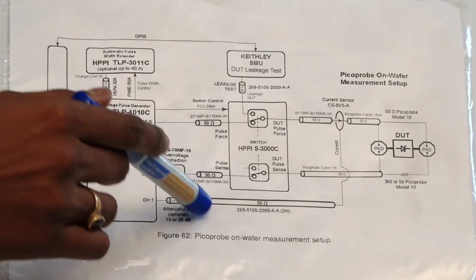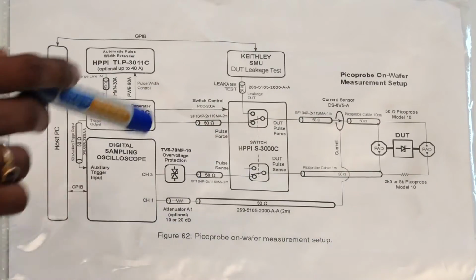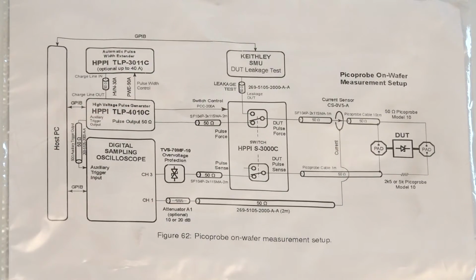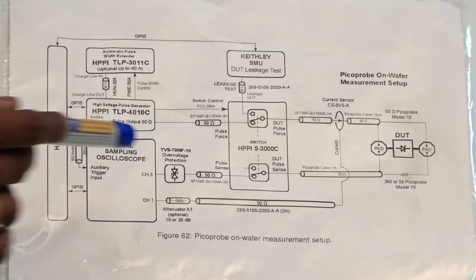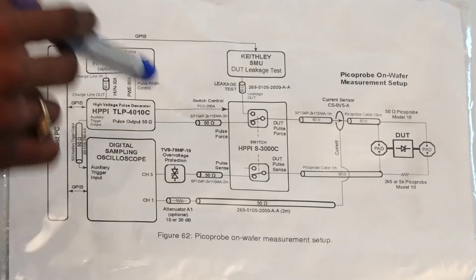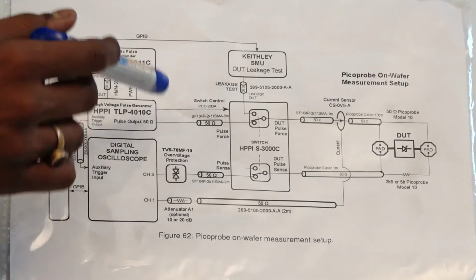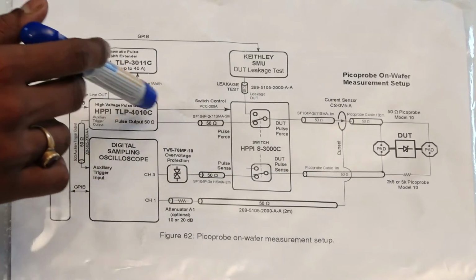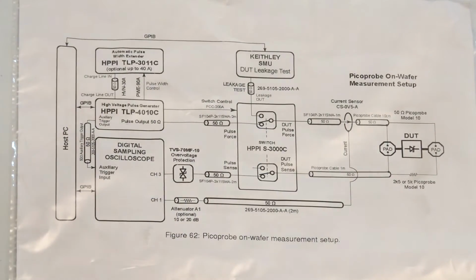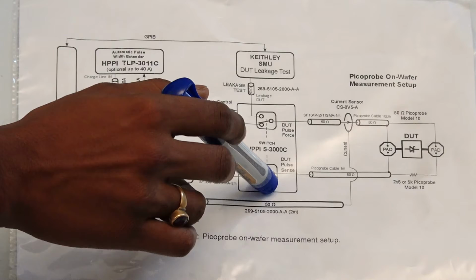So everywhere in this whole setup, the impedance of all the different lines is calibrated to 50 ohm, and a very important transmission line is used, and I'll show you the transmission line as well. So that's the importance of using a 50 ohm transmission line in the whole setup. Now this TLP generator is connected to a switch. This switch is important because it switches the whole measurement setup between different measurements that are going to take place.